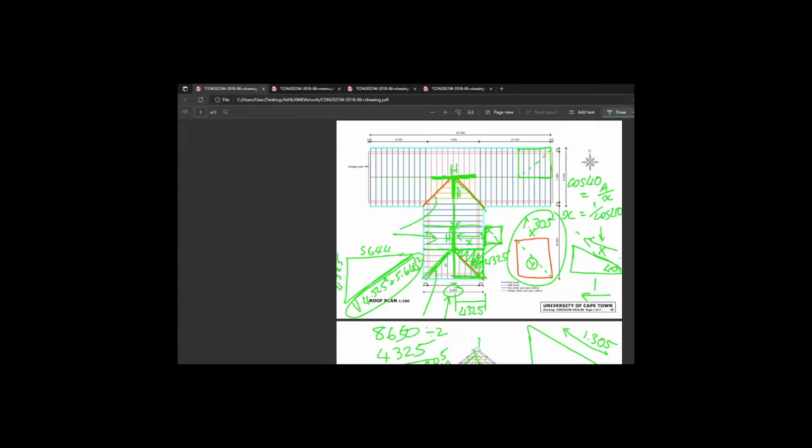If there was a tie beam that ran from the corner to the center, you would just take Pythagoras of the square to get this bisecting line. That would be a tie beam. But in the case of rafters, you'd need to account for the slope. You find your factor to get your slope so that this whole edge is raised now. You've got to visualize it. Flat square, these ends stay flat. Flat and flat. Okay? This end is now raised. And by what factor? Well, you have to use trig to find how much this face elevates. Let's go.